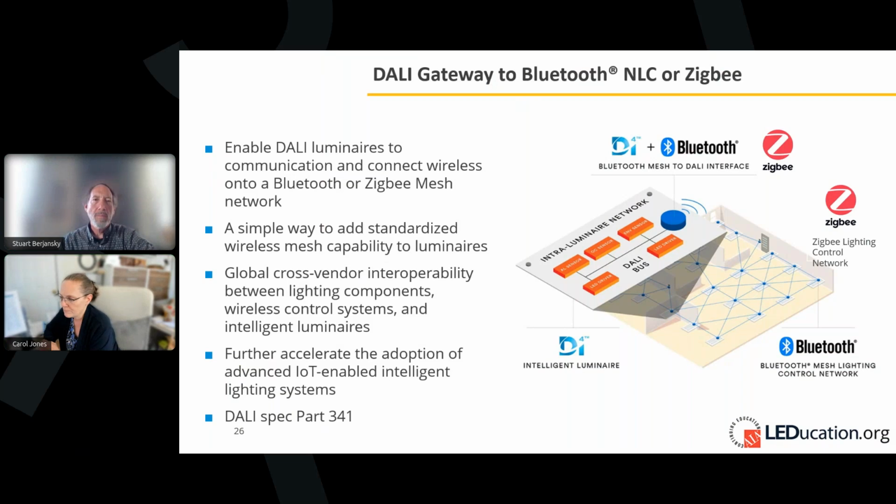Color is also another thing that I don't have a specific slide for, but keep in mind DT8. DT8 is the driver that gives you digital control of the color. And you can do your warm to cool in a way so that the fixtures match each other no matter what the types are. So you have different types of fixtures from different manufacturers, and the management of that, if it's digital, if it's a DALI driver, DT8 is the simple way to put it, that will be consistent.